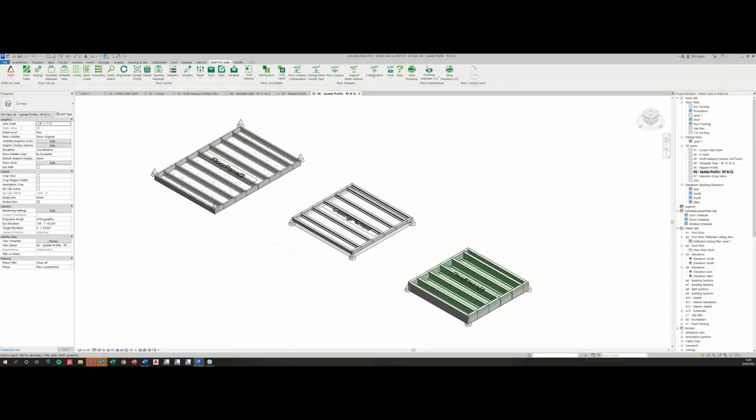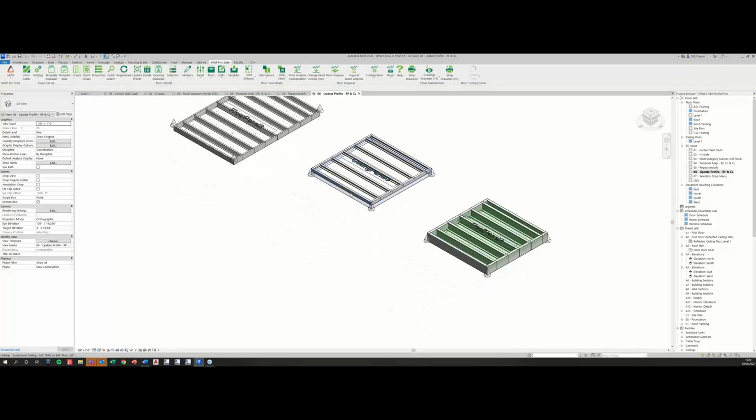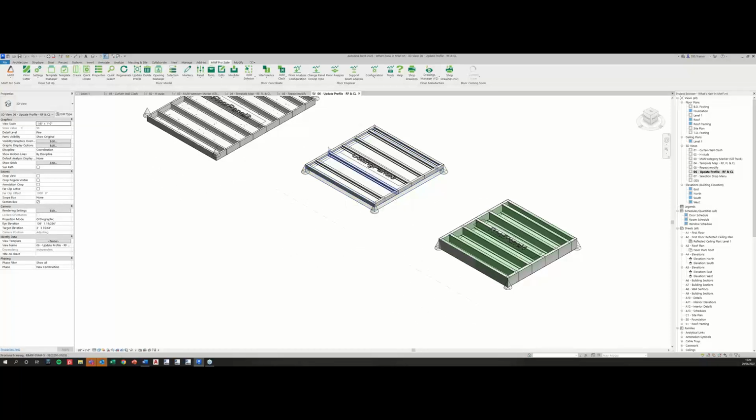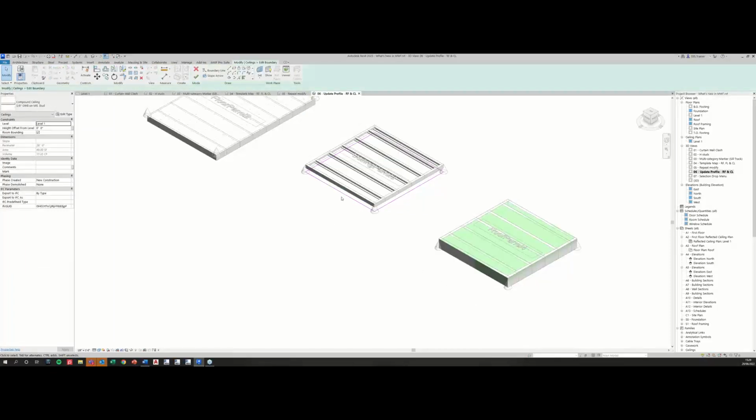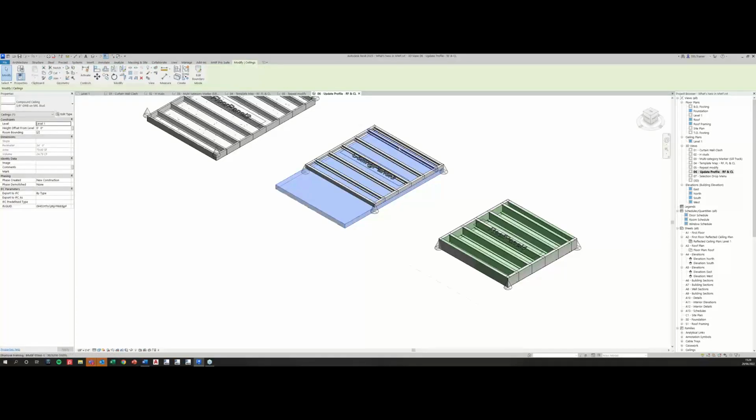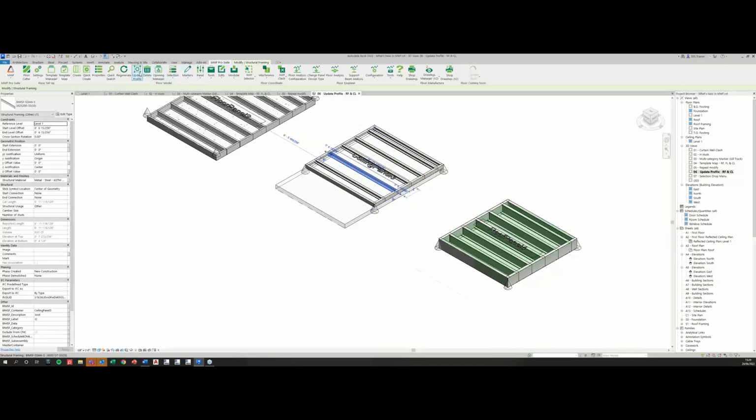Okay. I'll go ahead and make those changes to the roof and ceiling as well, just to show that we have that new additional functionality with those elements. So I can select my ceiling. I can edit the boundary. Okay, so I'm going to align it. So AL, select this point here. And then again, hit the green tick and regenerate.